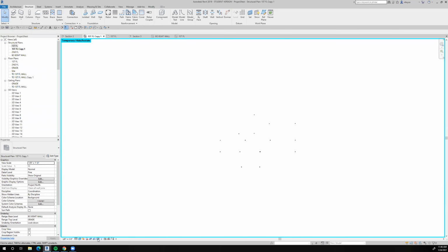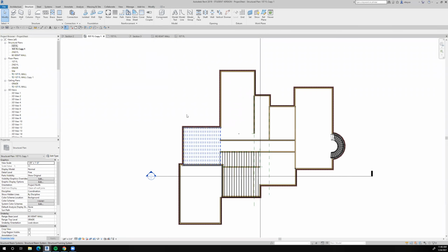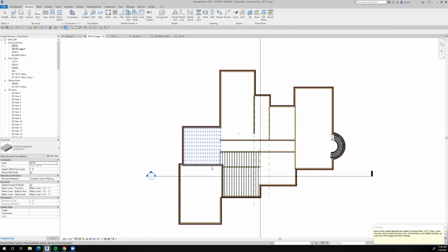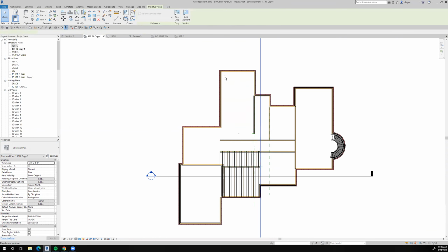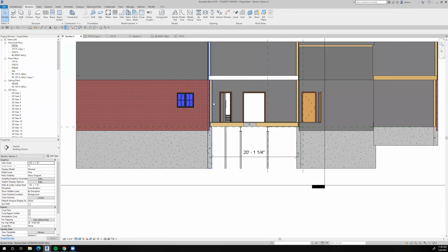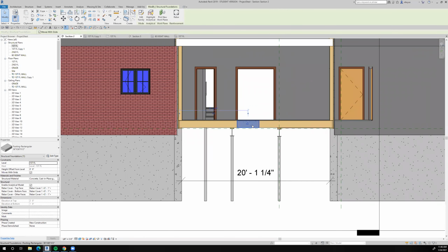All right, so let's see why it disappeared. We'll put the 36 by 36 inch in there, structure, isolated. I want 36 by 36 by 12. I'll put that right there. I can't see it. It's probably because I didn't pay attention to where it was located. So I'll go to the view, and sure enough, there it is. I want the level to be bottom of basement wall. Let's see what happens. There, it's perfect now.